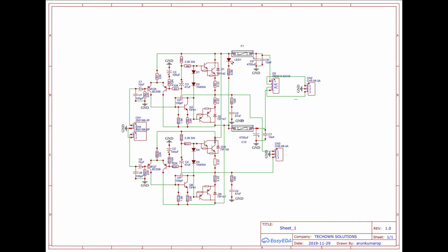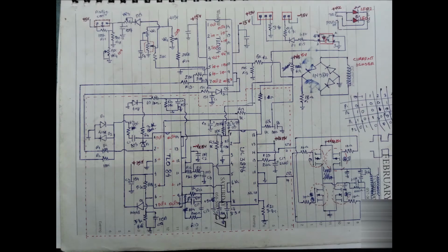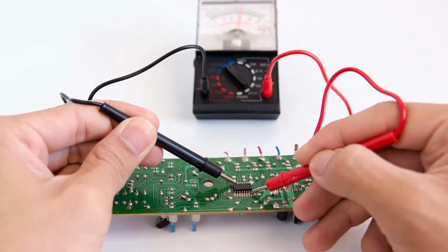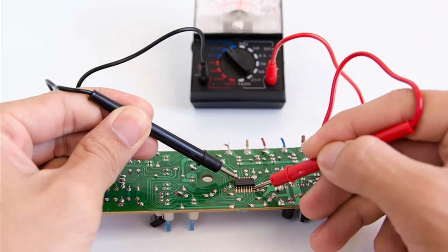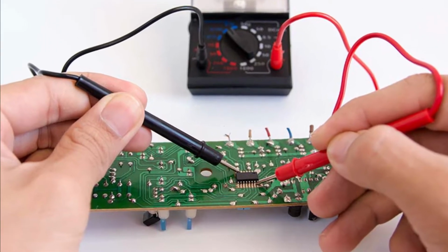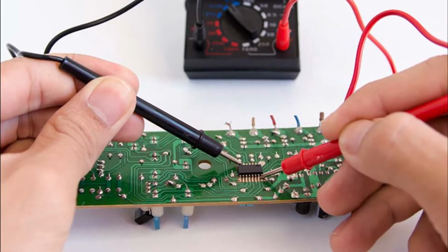Before you even begin to lay out your PCB, you must have a complete and accurate schematic diagram. Many people jump straight into the PCB design with nothing more than the circuit in their head, or the schematic drawn on loose paper. This just isn't good enough. If you don't have an accurate schematic, then your PCB will most likely end up a mess, and take you twice as long as it should.